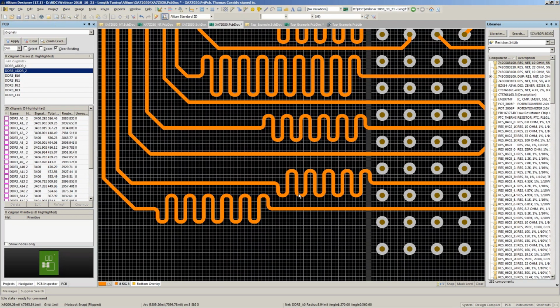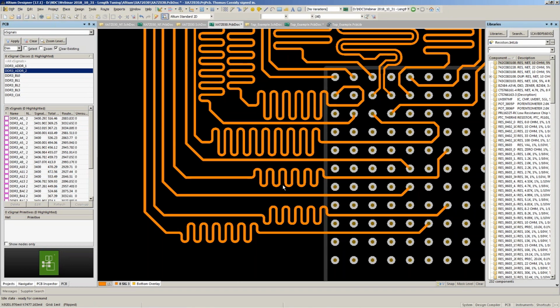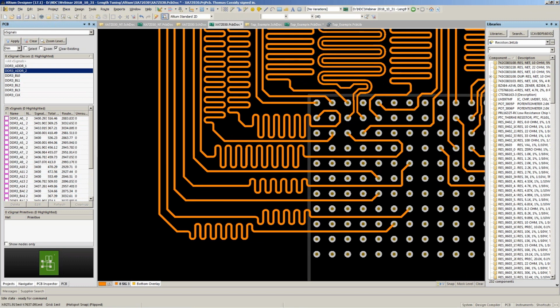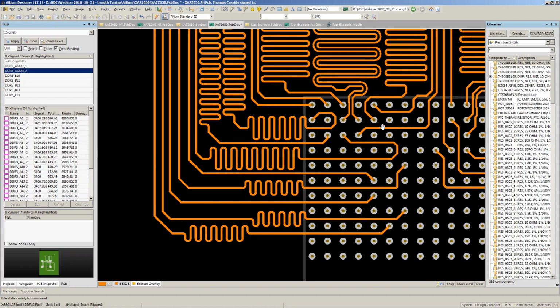Another trick I use is, if you're having to route or length-match two lines that are close, alternate where you do the routing or the tuning. So you started this one here, and then I started this one here. You can see I was able to overlap the distance instead of having to get them far apart. And you can see I did that here. I did these two here, but then I just didn't start this one until it was farther along. Once again, it may not be perfectly optimal, but you have to bow to real-world necessities.